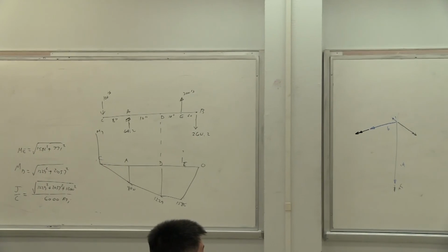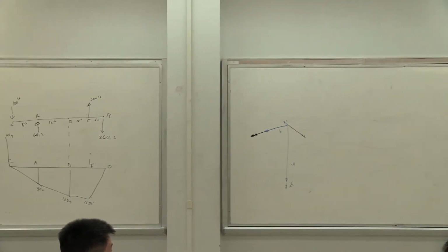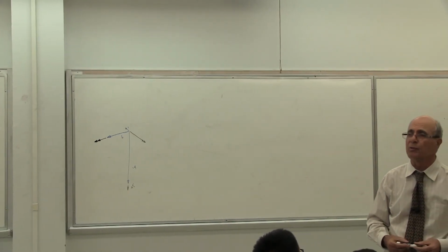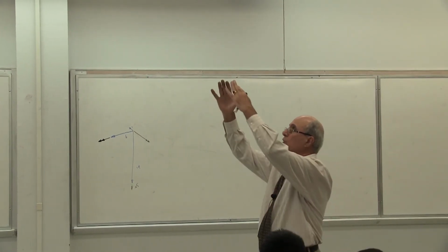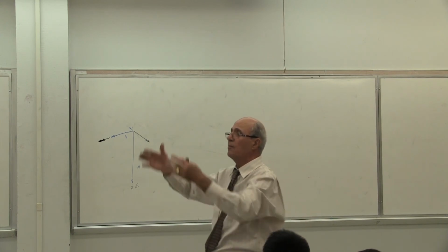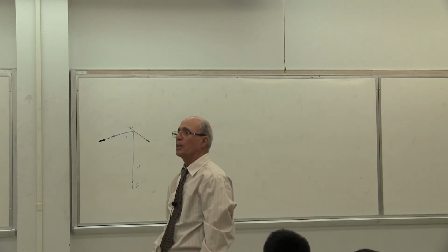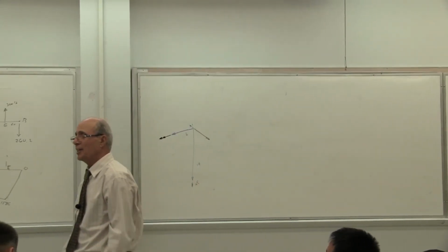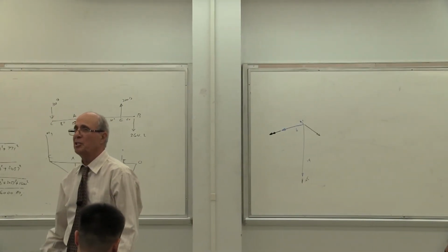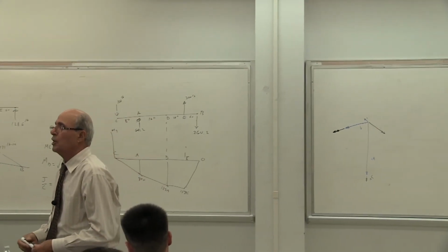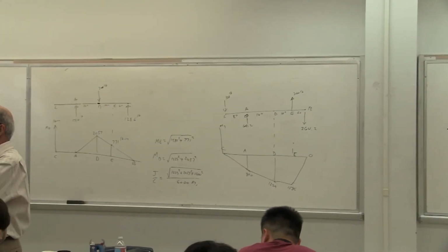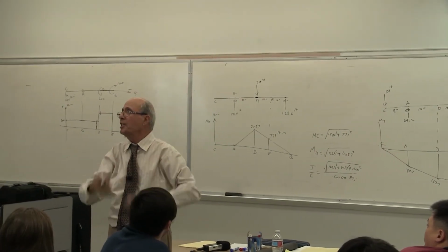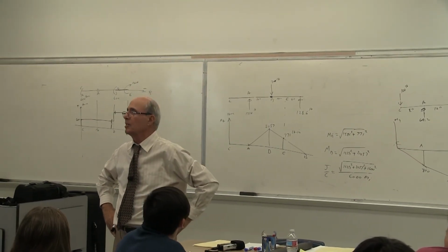If you make it safe here with a factor of safety of 2, everywhere else will be, of course, safe. This is how the design works. You don't just design it for every point. You don't change the column, unless you make lots of saving, then you may want to make a column like that. It goes down further because the more weight you get, you just put it in a shape. Is that correct or not? But typically, because of the costs involved, you just use the same size for the beam and column all the way, yes? But the maximum location is the design criteria, if that's correct.